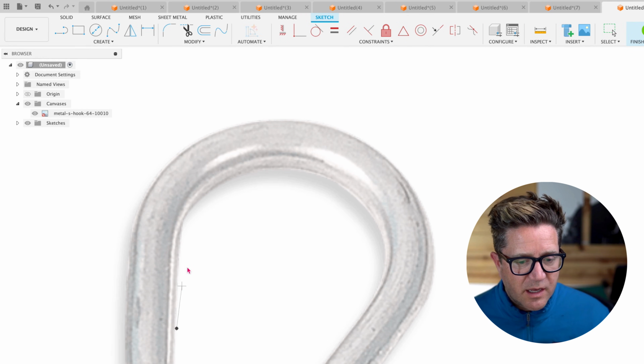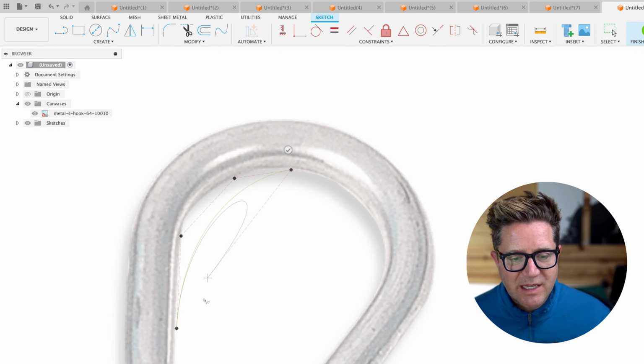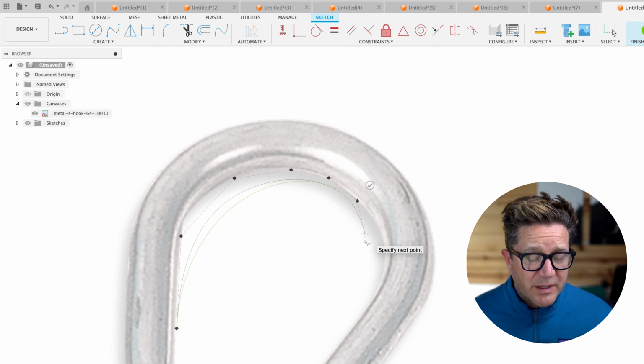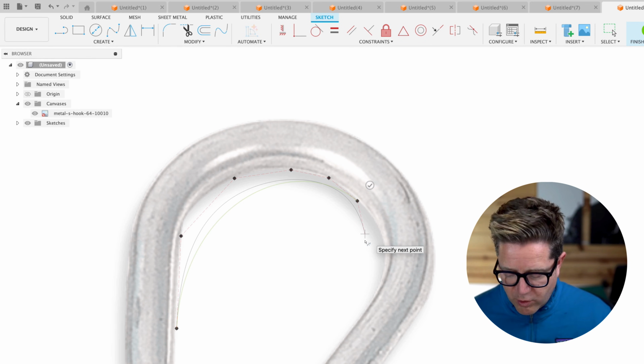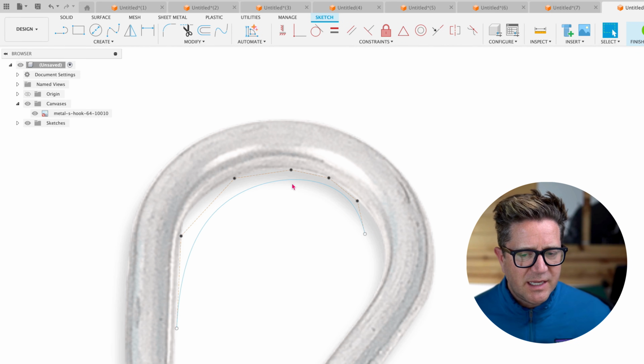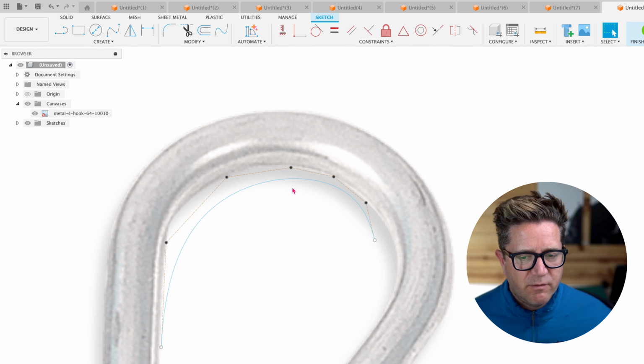This one is allowing you to place some points in space, and you can see that your spline is not even touching those points. It's just following this as a guide. So it's going to create a smoother curvature overall, but a little less control in that you're not placing each point directly on the spline.